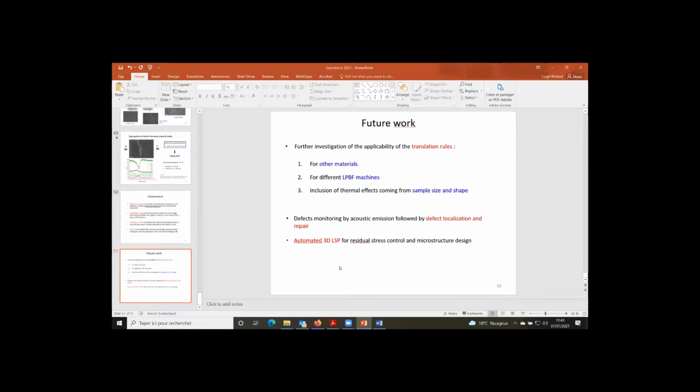Yeah. Do you actually also change the surface? I mean, is it sort of flattening the surface a little bit? Is that an additional benefit, or is the actual deformation negligible? Yeah, it does change a little bit the roughness of the material when you do it, but that's not the main advantage. I would say it depends on the initial roughness. It has many other side advantages. It does reduce the porosity size, which are below the surface if they're not too far away.